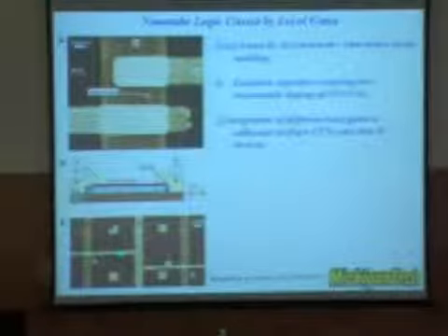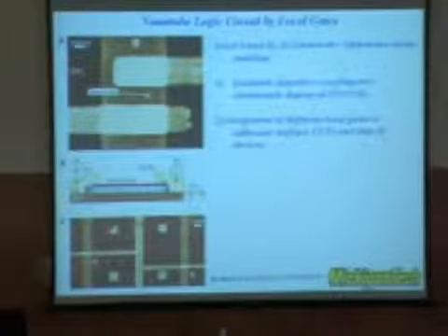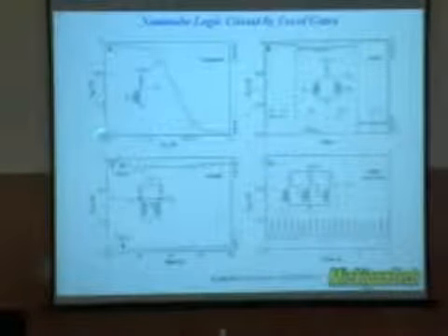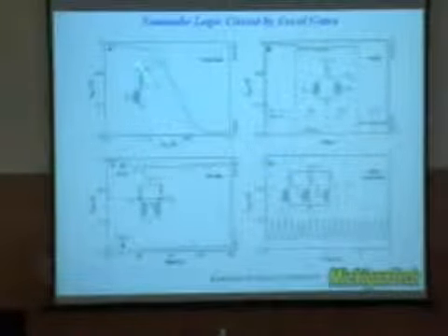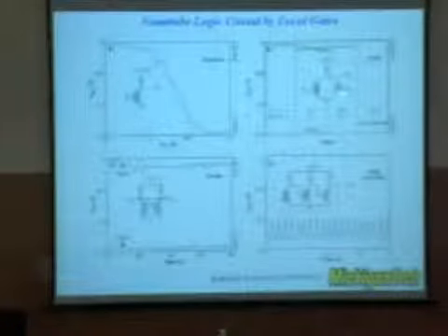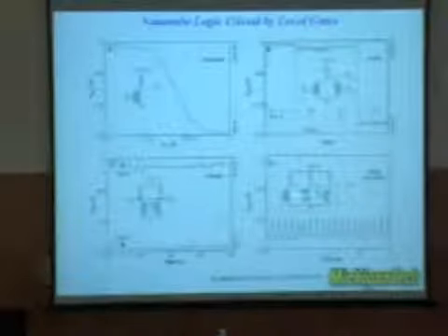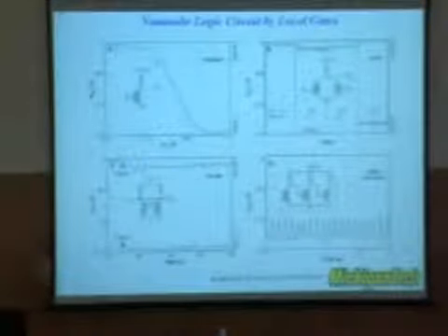And you will have a piece of carbon nanotube laying across these 2 electrodes, which are the source and drain here. So in this case, on one piece of the chip, you can have multiple nanotubes because all of them have their own gate. So if you do so, by using one piece of the conduction channel, you can form the inverter, you can use 2 pieces of them to form some of the logic gate or the memory device, and the oscillator as well.